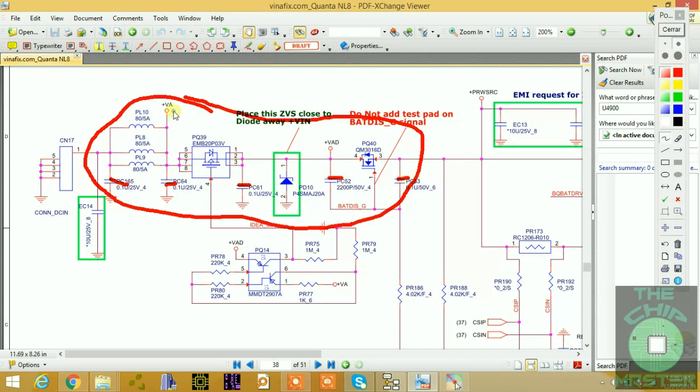And your decoupling capacitors and filter coils. So these, as I said, pass low frequency and block high frequency, and these caps pass high frequency and block low frequency of emission. Right? I wonder if you understand what I'm trying to say right here. So this is the reason why they've put these coils here, in order to protect the isolation and protection circuit.